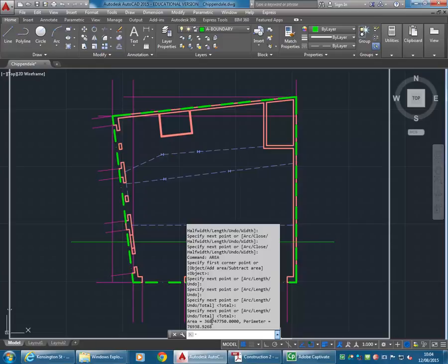Do you know maybe what a good benchmark for a size of a standard unit would be? So yeah, 100. That's right. 100's a good one. So 100 for a 2 or 3 bedroom unit is fairly typical. Yeah, it is. It's on the generous side, but 60 for a 2-bed is pretty tight. Yeah, 70 for 2-bedder is okay. 60 for 1-bed is all right. But there would be 2-bedders that are 60. They're just very tight. For a studio, anything under 50. Yeah, I mean there would be 1-bedders that are under 50, but that's pretty tight as well.